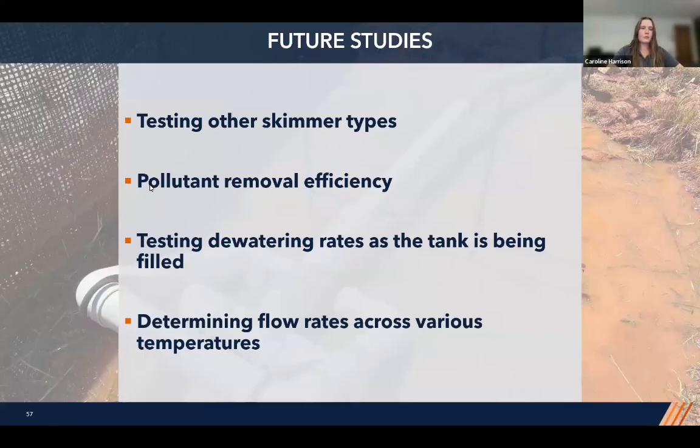Our methodology would be considered more conservative, since in real world conditions, the skimmer would be draining as the sediment basin or post-construction basin is filling as runoff is coming in. Here, the barrel is empty. So we would evaluate how performance changes as the skimmer tank is being filled, and also determine how different flow rates change across various temperatures.